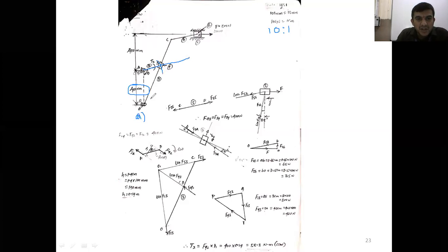Once you get point B, join O and B and extend that line. What is OC? How much OC is given? 800 mm. Convert to reduced scale, 10:1, that is 80 mm or 8 centimeter. Along this line OB, extend the OB line through a compass. Radius is 8 centimeter. Draw the extension of the OB line, and you get point C, right? After that, from here you can see the vertical height is how much?